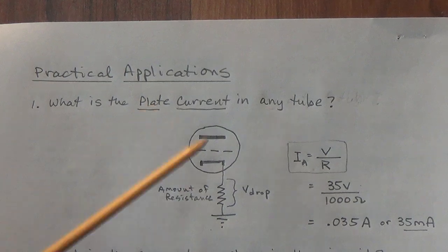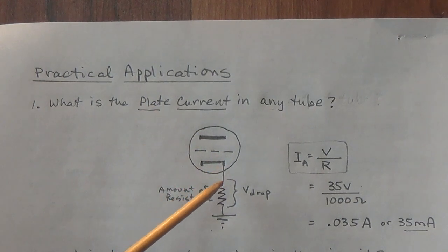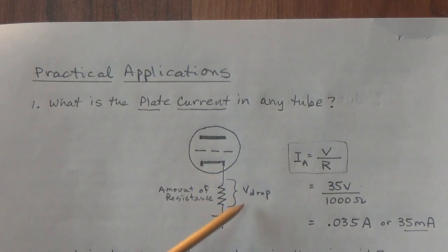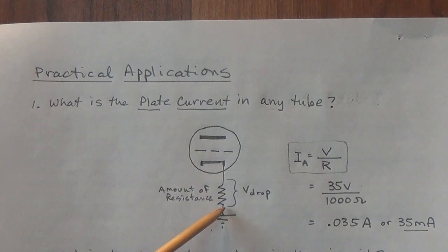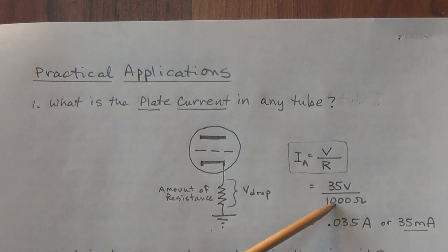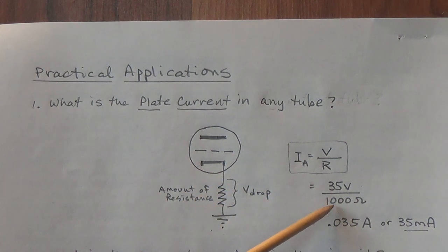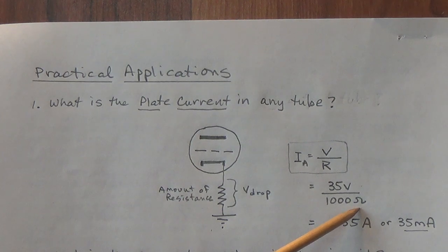And here's how. With the amp completely off and electrolytic capacitors drained, you clip your ohm meter on either side of your cathode bias resistor and measure the resistance accurately, say to 1 or 2 decimal places. In this case, I measured this one and it's exactly 1,000 ohms.